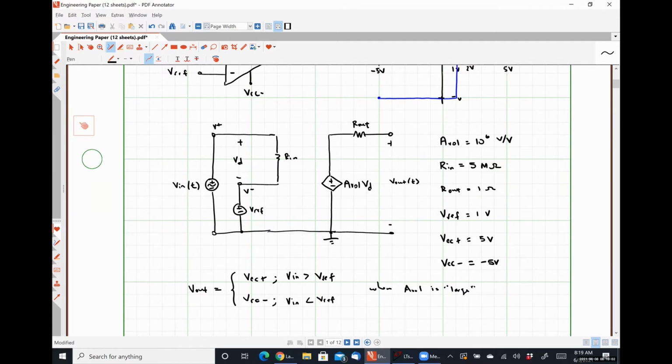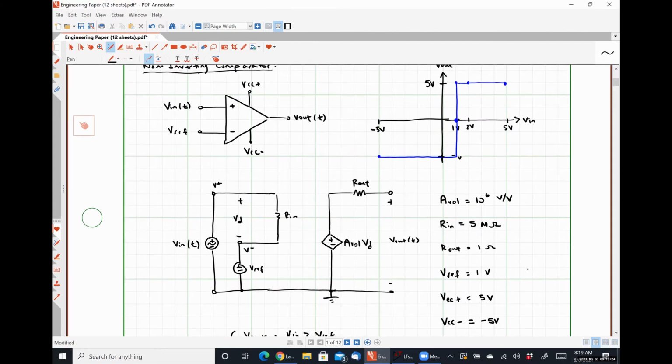The smallest open loop voltage gain op amp that I can think of is one that's used in video processing circuits, and it has an open loop gain of about 2,500 volts per volt. So it's still going to have a very, very steep slope. The linear range on that guy is a couple of millivolts plus or minus around 0, right? So on the macro scale, it's still going to exhibit pretty much this behavior.